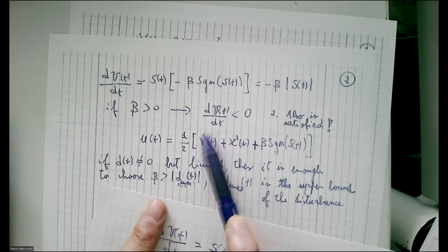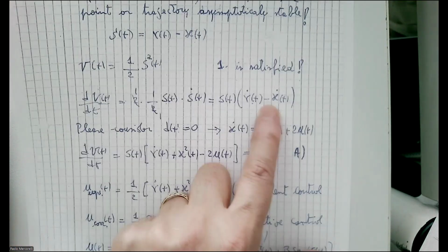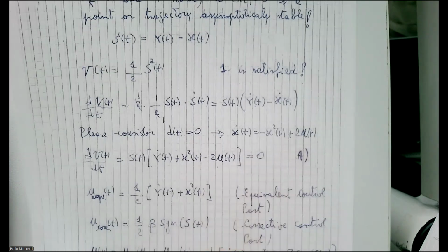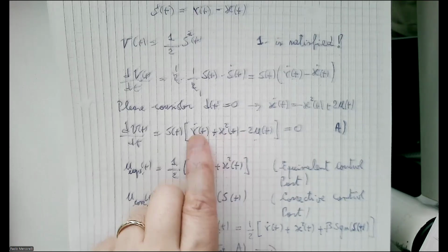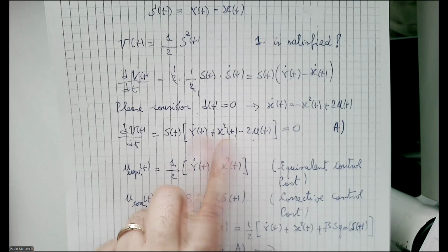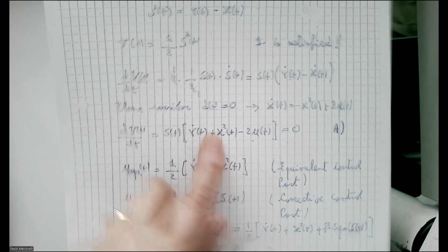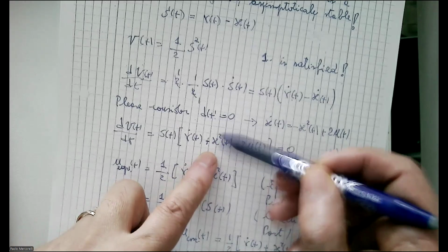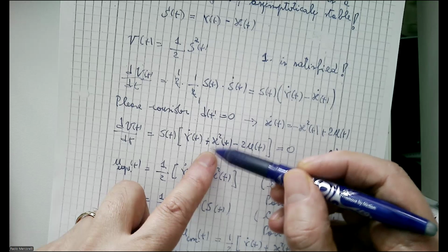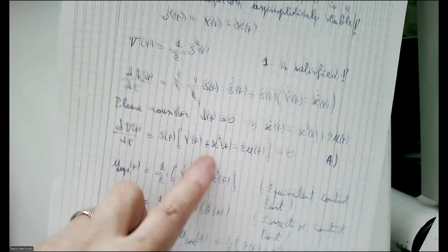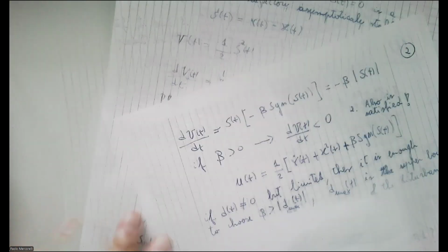This part here realizes the cancellation, because of this minus here, I will cancel these two elements if I know exactly r of t. But the coefficient which we have here, in the model we have a 1 multiplied squared, but I'm not sure if you have a 1 in the real case. It could also be 1.1, 1.2. This means the cancellation is not exactly perfect.